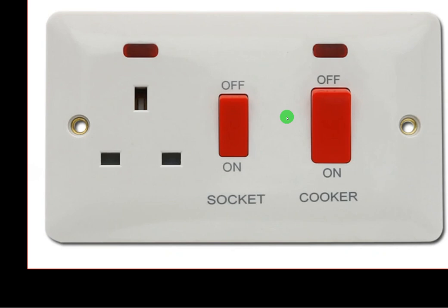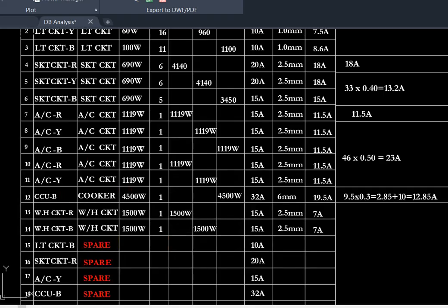But the 10 amps that we are adding to the calculation belongs to this. If this particular fitting does not have this, we don't need that 10 amps for our calculation. So let's go there. I will walk you through. Now come back here. The instruction said, whatever you have here, subtract 10 amps first and keep it aside. So let's subtract 10 amps here and keep it. If we do that, we're going to have 9.5 amps left.